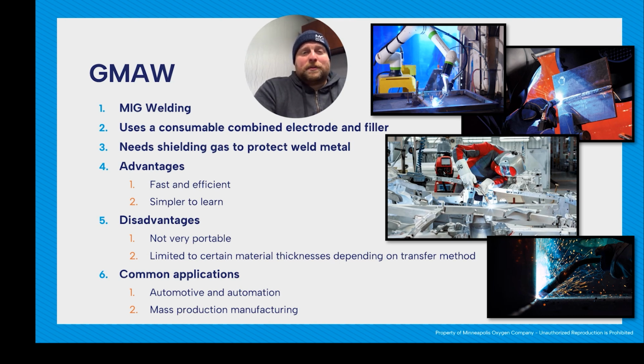One note on the name. GMAW is gas metal arc welding. MIG is metal inert gas welding. The reason we go to GMAW now is because we can use active gases, like a 75-25 gas mix, which is very common. That's 75% argon, 25% CO2, and that 25% CO2 is an active gas. So GMAW is a more accurate name than MIG, but you're going to hear MIG everywhere. And you'll hear me just kind of switch them out as I feel when I'm talking.